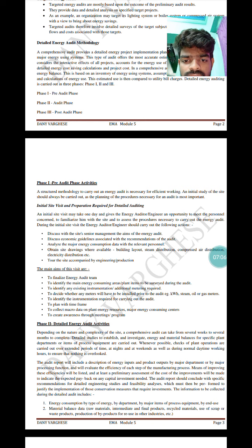The main aims of the visit in the pre-audit phase are finalizing the energy audit team, identifying the main energy users, and identifying the infrastructure needed, such as the meters to be installed prior to the audit. And next we plan a time frame to collect the macro data and to create awareness.